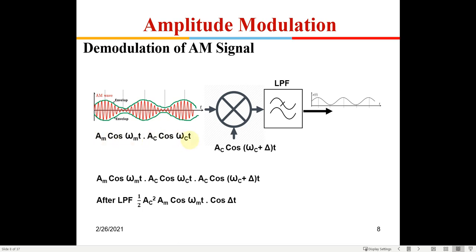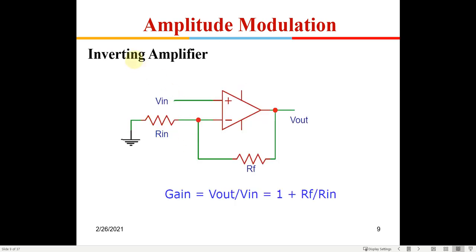So let me go back to our design and change the way we are transmitting signals. For that, let me explain what a non-inverting amplifier is. I had written inverting amplifier, but this is a non-inverting amplifier, where I have an Rin and an RF. Following the same philosophy here, where the input voltage at the plus and minus of an op amp remains the same, the voltage out here will be Vin. So the current which will flow into Rin will be Vin divided by Rin.